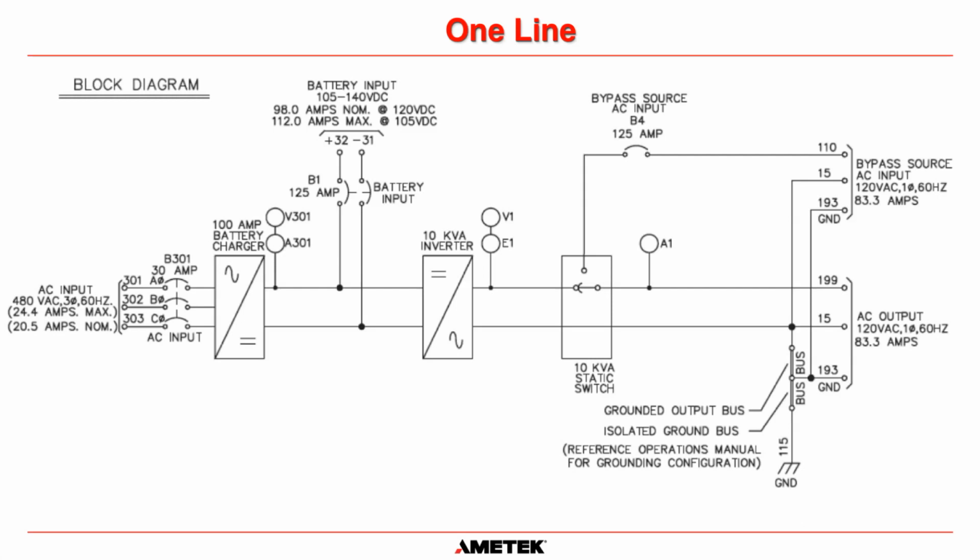And do remember, we have a positive and we have a negative. I know it seems the most basic thing to say that they should be connected correctly, but over and over again, we go out to do startups in the field and we discover that somebody has connected the battery to the UPS charging system with reverse polarity, and it causes all sorts of issues. So please don't do that.